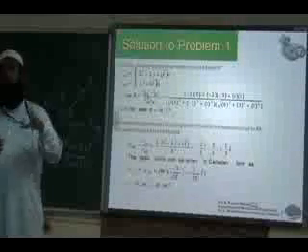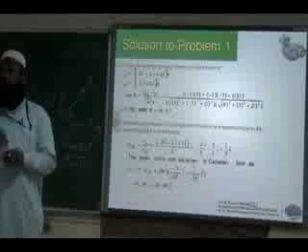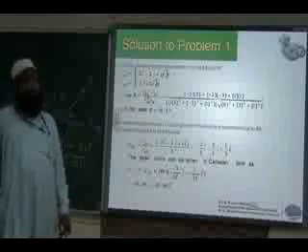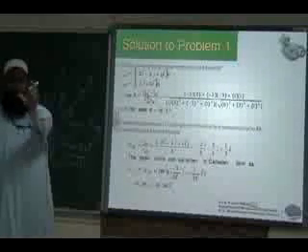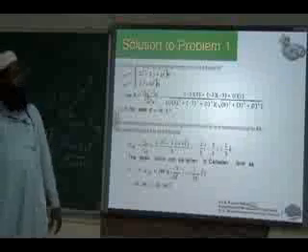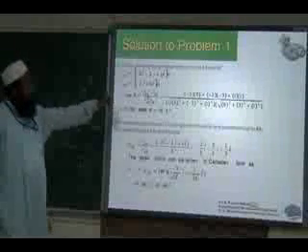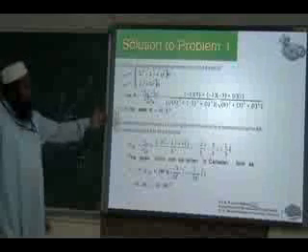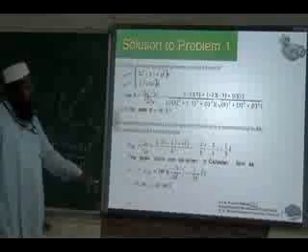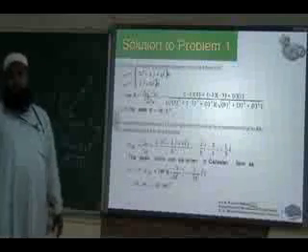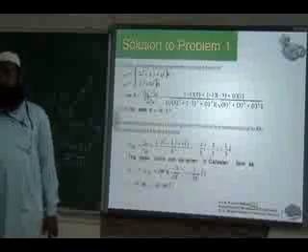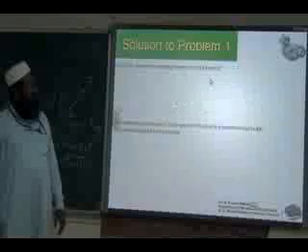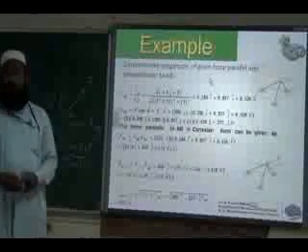In some problems, you can even consider the unit vector along AB, unit vector along BC, like that. Unit vector can also be considered to find the angle. The magnitude may change, but the angle can be found. So we have considered here the position vectors between AB and BC to find the theta. After finding the theta, we apply the concept of dot product again to find the forces parallel and perpendicular to the two given axes, to the required axis.